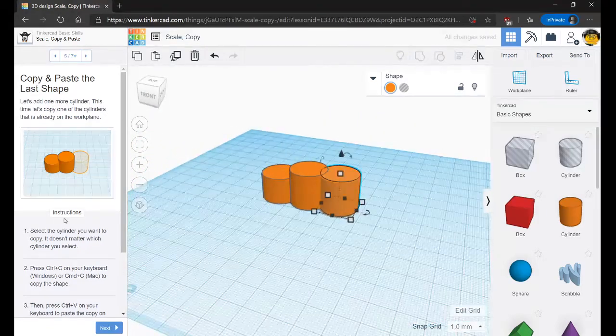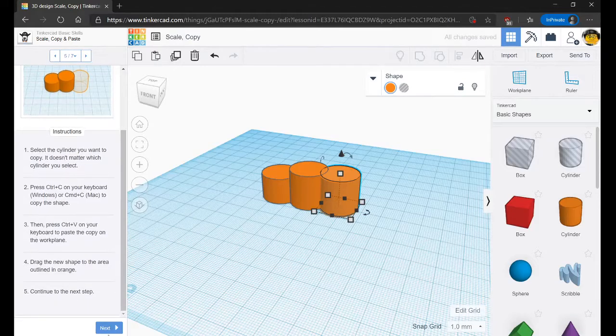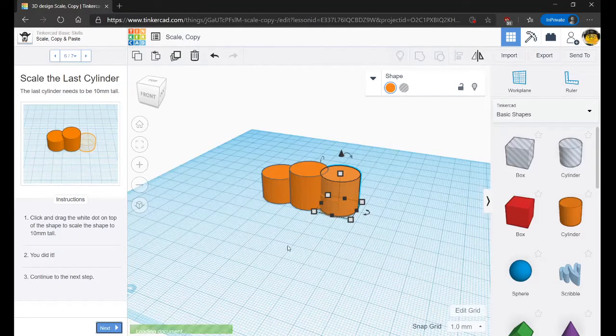One thing to note is that it will show you the dimension based on your camera angle or what you currently have selected, so just keep that in mind when you're changing them, if you're like me and prefer to type them in. So for this last step, we're going to simply shorten the cylinder down to 10 millimeters, and once we do that, we've completed this step.